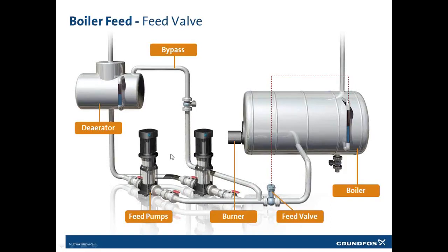That of course means that we are pumping excessive amounts of water, and that gives us a higher energy consumption. Now that's not normally what we are concerned about in boiler feed solutions, but we are pumping excessive amounts of water and using more energy than needed.